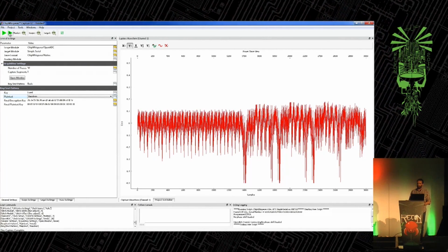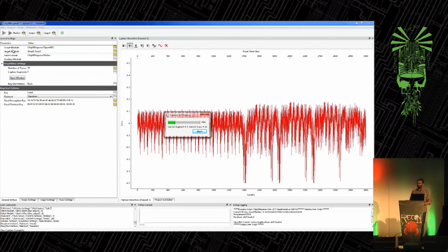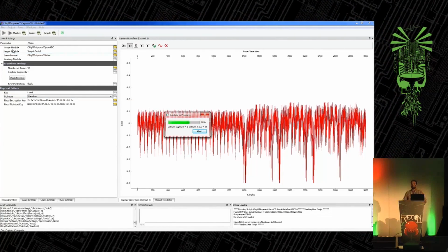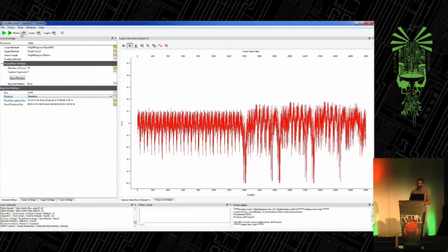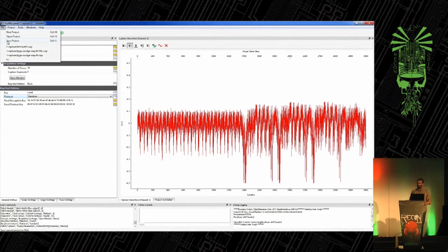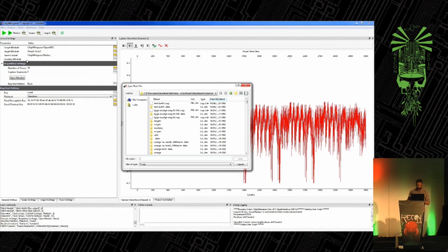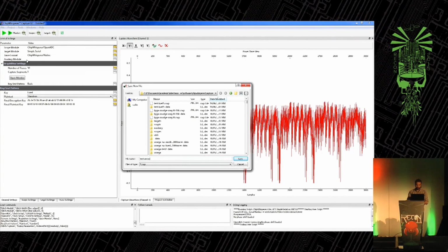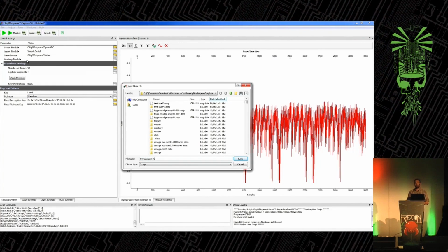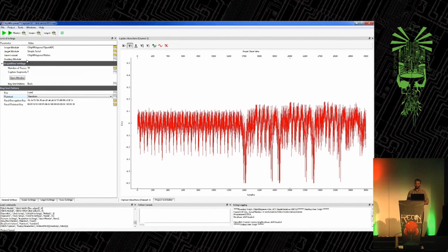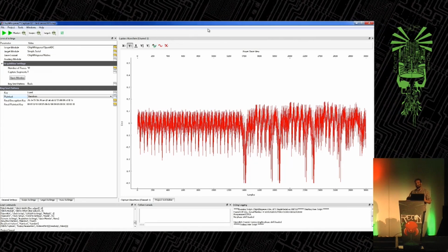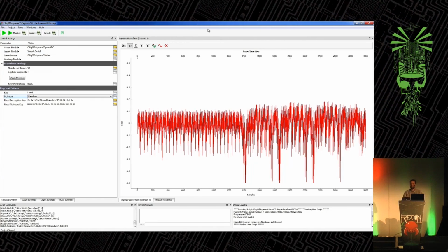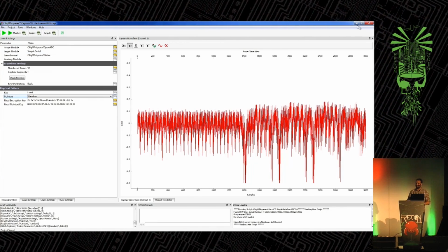All right, so what we're going to do is capture 50 traces. So it just sends 50 messages to the device, encrypts them, and monitors the power while it's doing that encryption. And I'll save it as recon2015. There's no undo in this GUI, so I don't need undo. And in fact, you can't close a project and reopen a project without closing the whole thing. So it has lots of features like that.